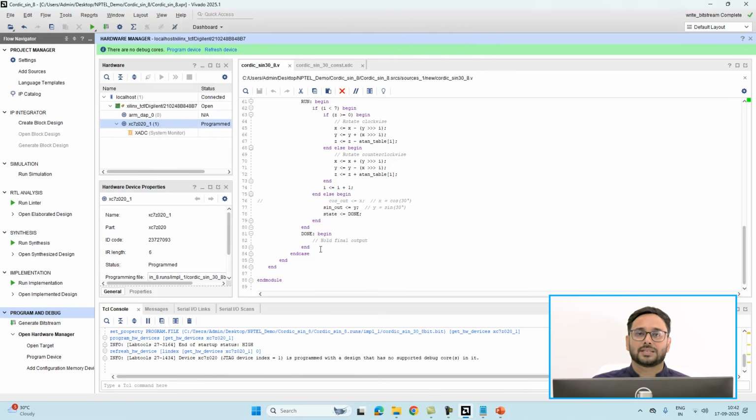In this demo, we have seen first how to read a text file stored somewhere on your computer in the Vivado program. Second, we have implemented the CORDIC. Initially, for the simulation I took 16-bit, executed it for 10 iterations and got the output. The output was not exact, but approximate. It will have some error, right? Because we have converted the trigonometric function into only addition and shift operations. For every iteration, it will have 1 shift and 3 additions, and one lookup table is used to store our theta values.